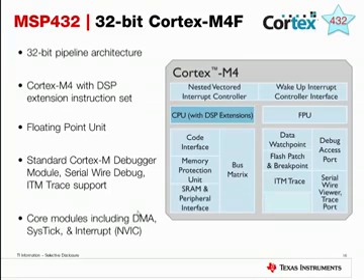The CPU uses a Harvard architecture, which means that it has a separate instruction bus and data bus. This allows the instructions and data accesses to take place at the same time. As a result, the performance of the processor increases because the data accesses do not affect or interfere with the instruction pipeline. This feature results in multiple buses and interfaces across the Cortex-M4F, each with optimized usage and the ability to be used simultaneously. However, the instruction and data buses share the same memory space. This is called the unified memory system.